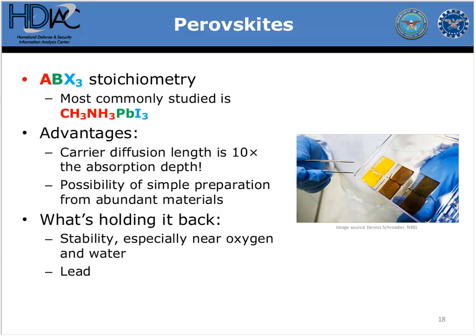But there are still some challenges to overcome for sure. Stability is the biggest one, especially near oxygen and water. We've seen perovskites start to lose efficiency after a while, after testing. Some light-soaking, hysteretic behavior. That may be overcome, we'll see. Certainly better hermetic seals will help with that.